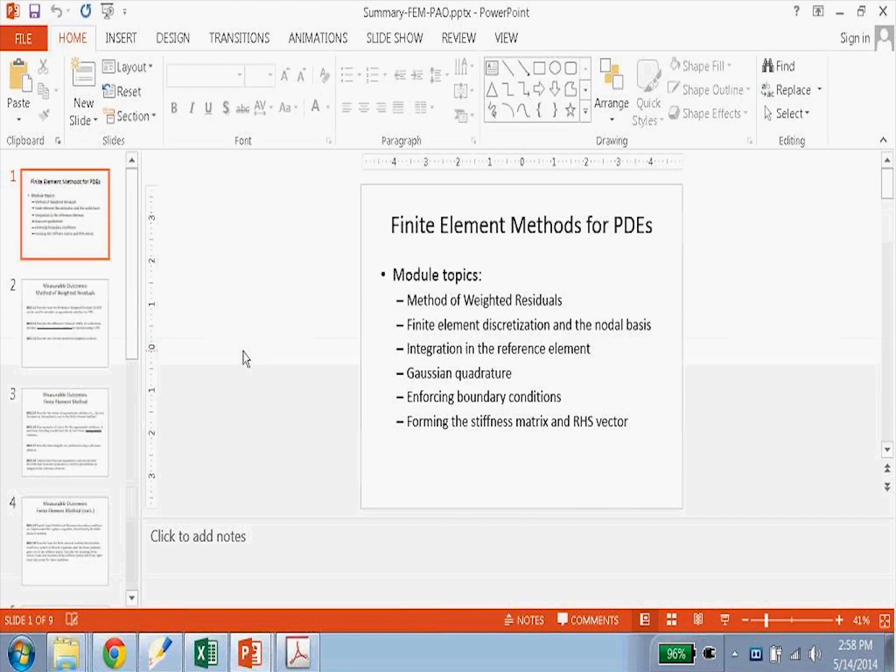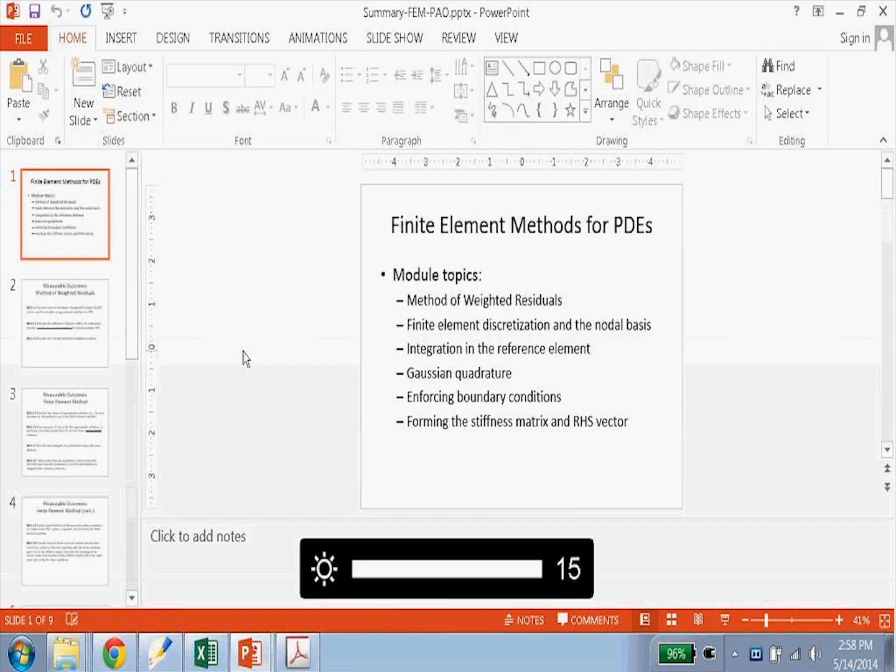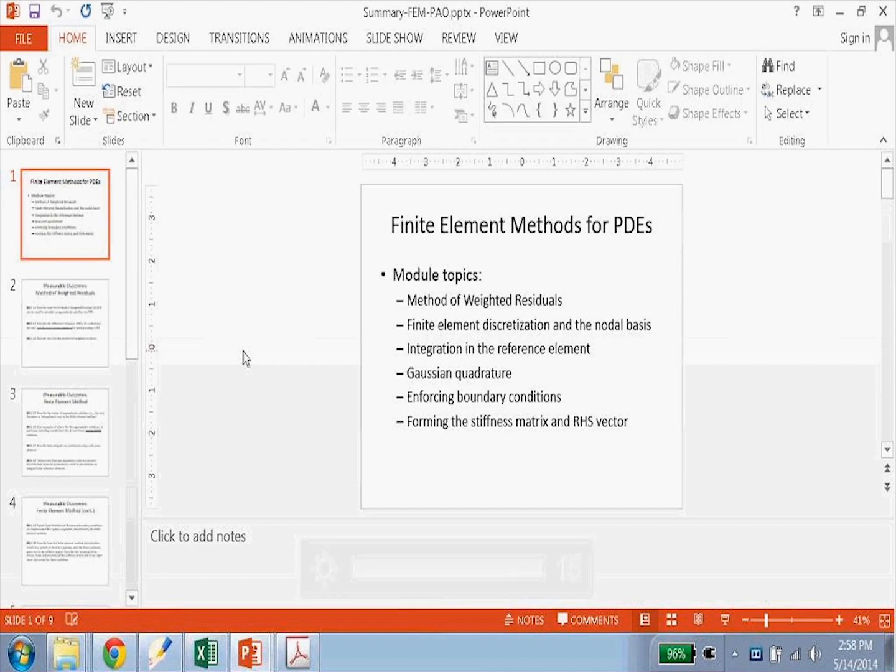Okay, so it's one of those things that seems a little bit messy when you see it written down, but the reality is it makes your code really clean, right? Because you just introduce these mappings, and then every single integration in the code takes place over the reference element. You just got to account for the mapping from whichever element you happen to be in through the determinant of this matrix. Is that good?